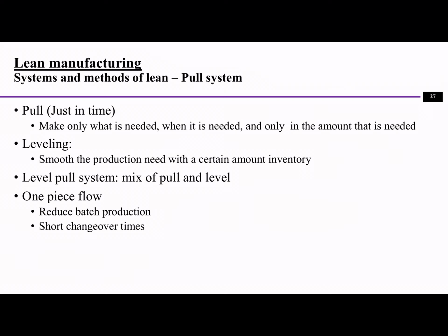That makes it a better system, and an efficient one, because it's using the pull system to drag the production, but also it has a little bit of leveling. That means if some situation happens, the system is resilient enough to deal with it. Right? Well, the most ideal case is one-piece flow, which means no parts are sitting on the shop floor. Everything we are doing is one piece. But that is very ideal.